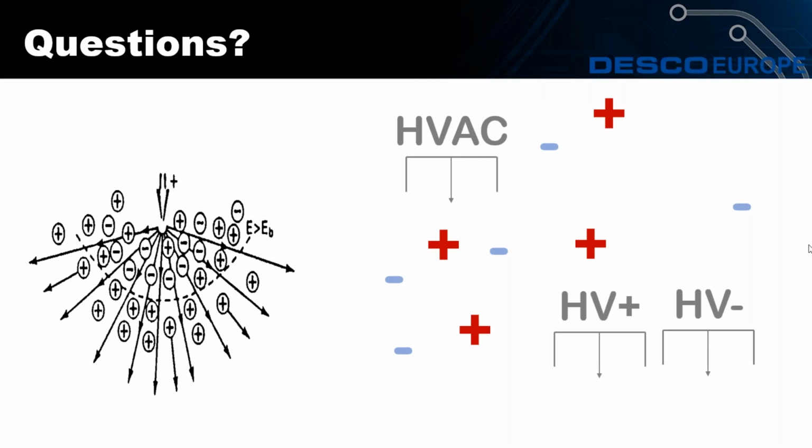So it's not a suitable alternative to grounding the work surface and the operator. Grounding is absolutely your first approach, and then ionization, as Vaughan already has mentioned and we'll come back to, is to do with dealing with isolated conductors and insulators. Anything that can be grounded should be grounded.